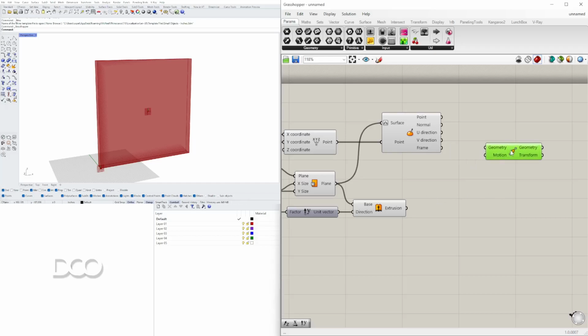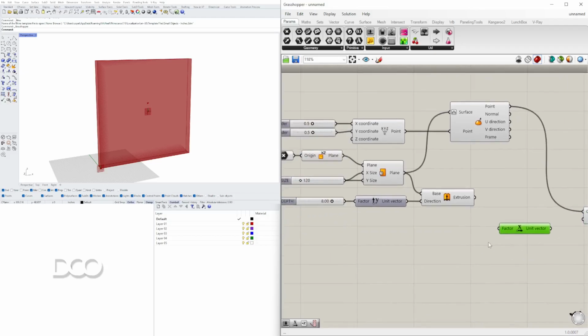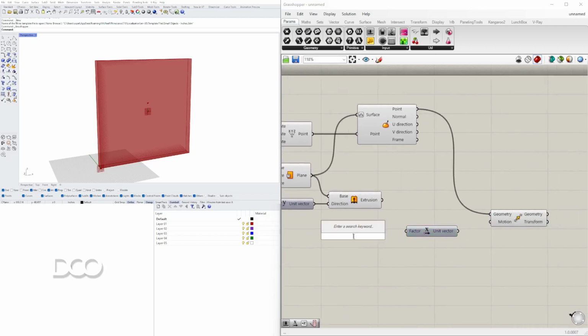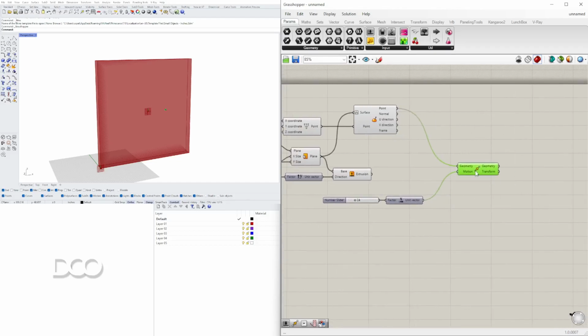Now we'll take this move and we'll move the point. In which direction? Well, we can use this plane as a reference plane, or we can just move it in the positive X and negative X. I'll bring this down here and we'll go positive and negative using, let's say, 24. Positive. And then I'll create a new copy here and then bring in a negative.